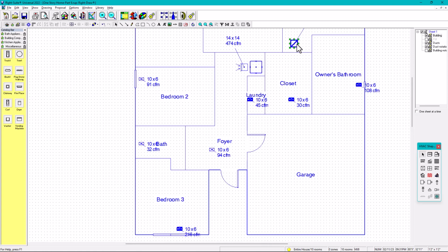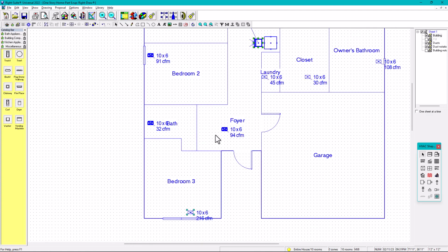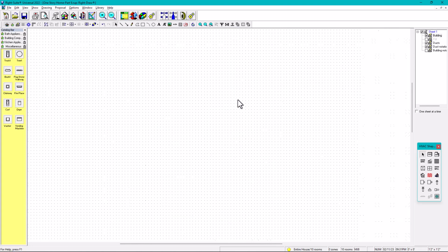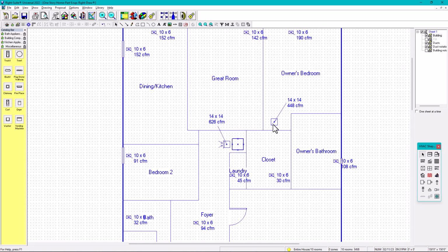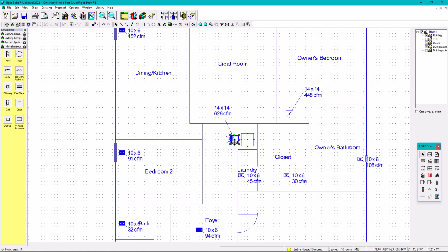So we're going to click in here. That's wrong. See? No, it's not wrong, but this supply register is closer to here. So it's better if it's associated with this one. So what we're going to do is click this return, hold shift, and then select this. Now what we're going to be doing is linking these two, so that's going to be supplies register link. There we go. We have it now. So this is very well linked. See, linked. All right. So that's amazing and that's very good.